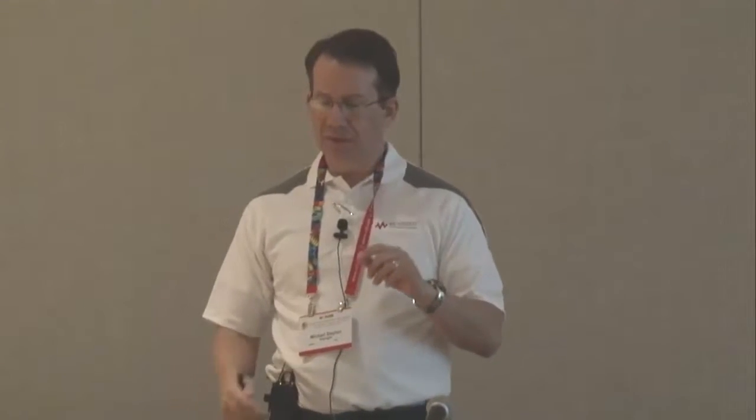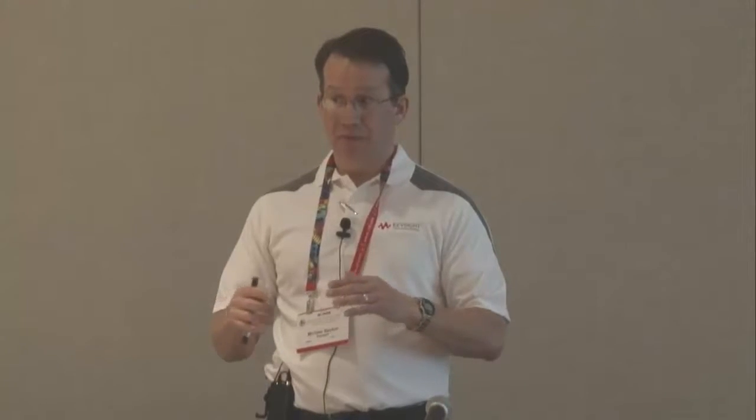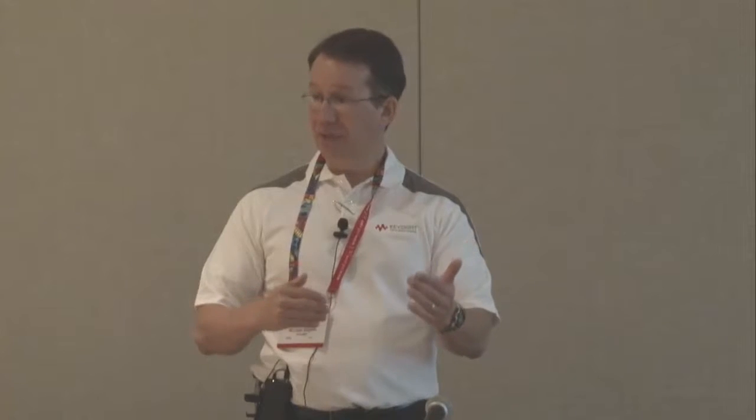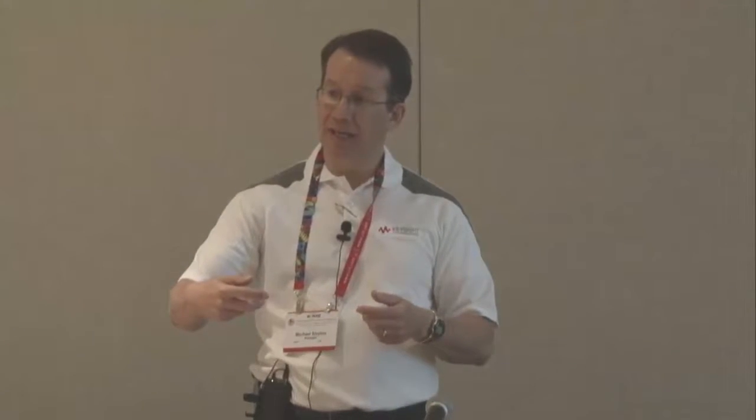Okay, so that's, maybe we talk about it afterwards because that's a completely different thing. But first of all, it's a completely different mode. If you want to think of it as an app or a personality, that's usually an extra option, where we have a noise figure mode, and that includes different software, but it uses most of the same hardware, because a spectrum analyzer is a very sensitive receiver, but it also has some special noise source voltage sources, typically in the back of the analyzer.